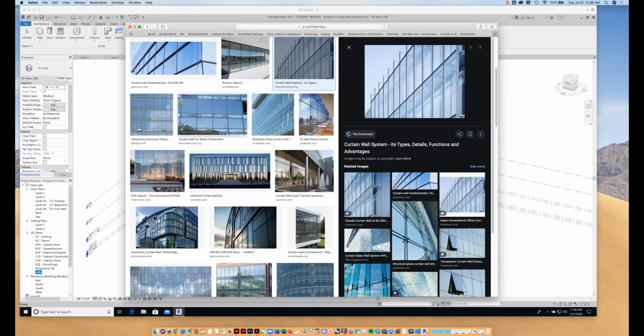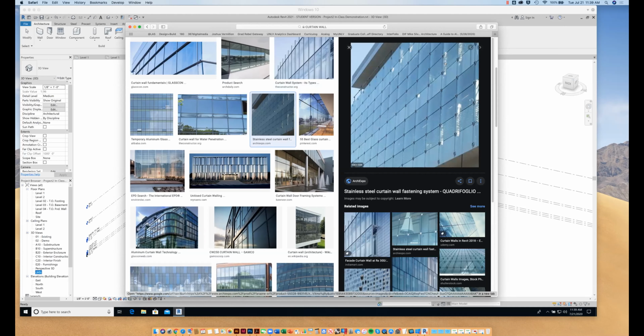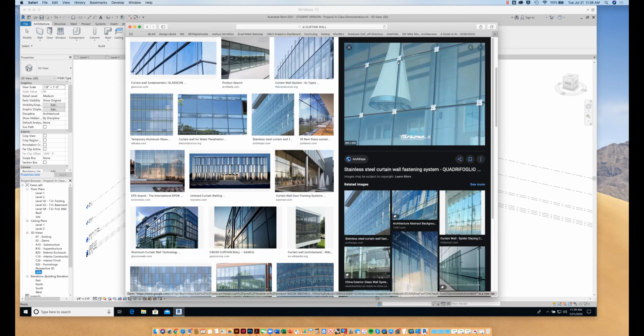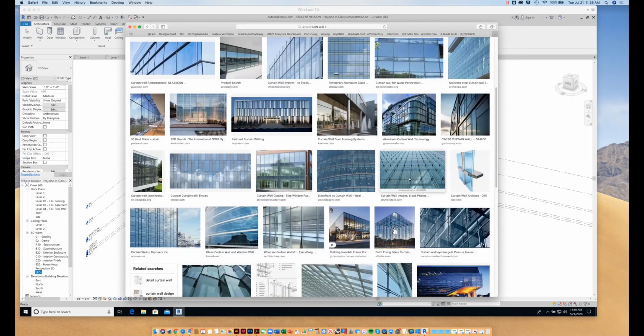And there are lots of different curtain walls now. Some have mullions, and some are mullionless, where you just bolt hardware through, clips, spider clips, and those sorts of things. Instead of mullions and panes, you might just have a silicone joint, basically a gasket. You can look at different glass systems if you're really curious about that. But that's what I mean by curtain wall system.